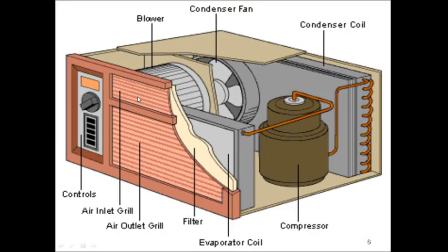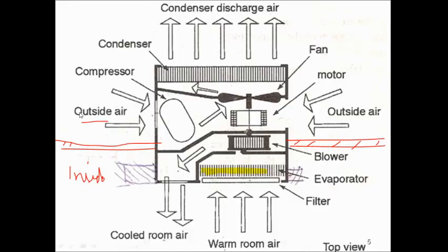You can see here, from this and this, both sides there is an opening on the rear side of the AC, left and right. So this fan sucks the air at ambient temperature and makes it flow past the condenser coil. In this process, the refrigerant vapor gets cooled down and then is converted back into liquid refrigerant. In this way, this whole system works like a heat pump.